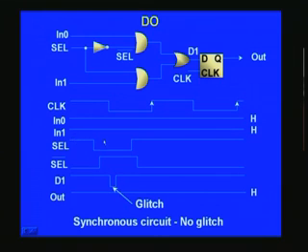and this is caused because you can just see here, this is 1 and this is 0. So being an OR, 1 plus 0, or the other way, is going to be 1, just as here also 0 1. So all through it will be 1 except for a small interval here. At this portion it is 0 here, and it is also 0 here. So this 0 will produce 0 right at the D1, and that is how you get a glitch here, and this is contributed by this inverter. It is the propagation delay of the inverter which is responsible for creating this.